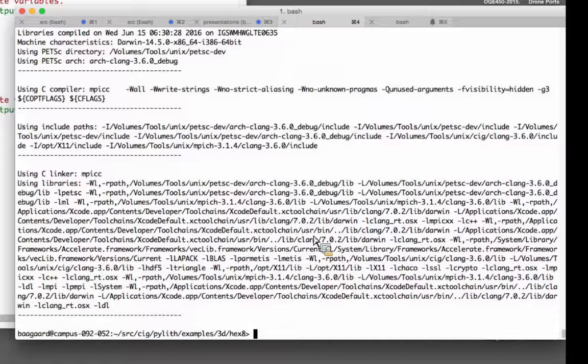We can compute the slip based on the displacement field, and we also have the Lagrange multipliers with the traction. So we compare the Lagrange multipliers to the friction tractions that we get from the fault constitutive model for that given amount of slip, which in that case is usually 0 because we're stuck.